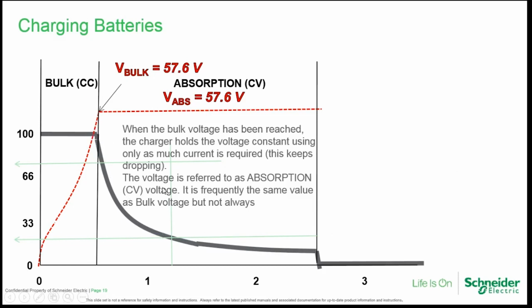It's kind of like it's got a brand new cheap plastic sponge in there, and it takes time to actually absorb the water. So that's why we call it the absorption stage. You can't rush this, unfortunately. So we do our very least to keep the voltage there. And then when we notice that we don't need hardly any current anymore, a certain threshold, then we say we're done. At this point, the battery is nice and fully charged.